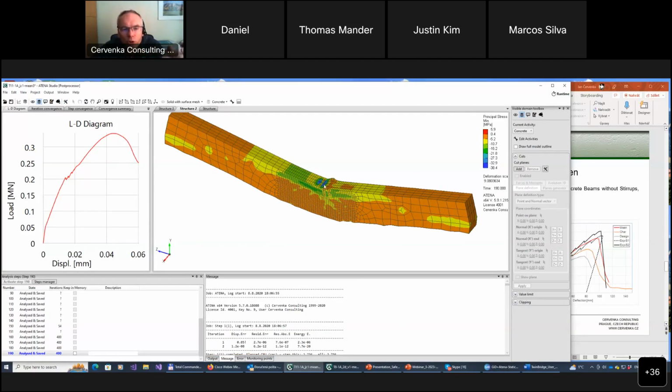So this is what I was talking to you about, that looking at the stress by itself is really not good information about what is happening in concrete, because here we have some higher stresses, and in these yellow areas it seems like, okay, it's good. There is just minus 10. So we would think, oh okay, nothing is happening, but this is not true. We have to understand we are in post-peak, and actually the stress is lower because the concrete is actually crushed. Due to softening, the material has lower strength.